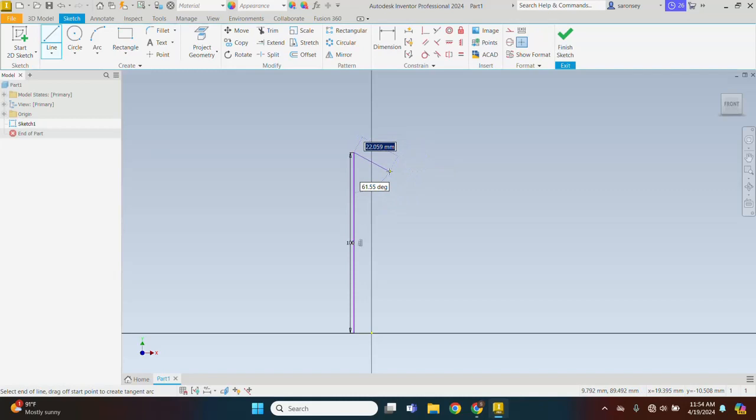And then notice we are still in the line tool. The line tool is still active. So you can specify the other direction you want the line to go. If you want it to move perpendicular to the line you initially drew, you notice that it shows you the angle between the two lines, and then also you can select the length of the second line you are drawing. So let's make the second line 100 also. Press enter, and then with that same procedure you can come down.